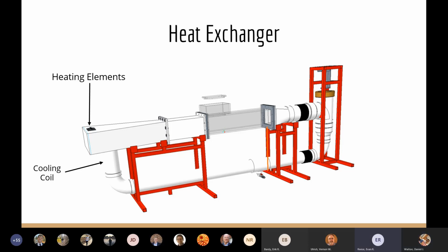So I can go ahead and talk about that. Dr. Anderson will put small reflective bits in the water that can be picked up by the camera with the light shining on them. And knowing the frame rate and the time it takes for it to get across the screen, because those cameras are very sensitive to time measurements, that allows them to calculate how fast the flume is going.